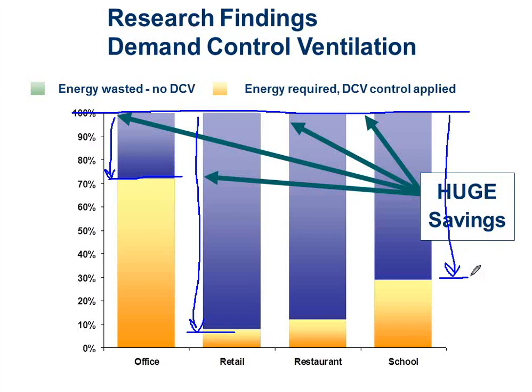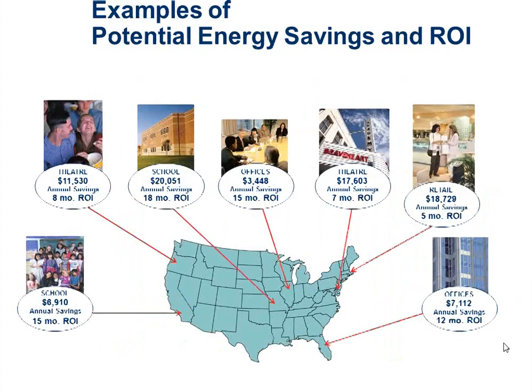On an 8-hour day or 7-hour day, they're only in their classroom for a few of those hours. Same thing with the gym and the lunchroom and the music room and all those other places. They're not fully occupied all hours of the day. The kids are moving throughout the building, right? And everybody's got to be somewhere in the building, but you can't be in 2 places at once. So if we can figure out where you're not, we can cut back the ventilation rate temporarily for that particular space. That's kind of the idea with the schools there. It's a very large potential savings.